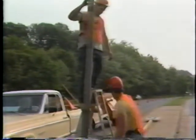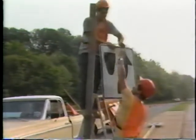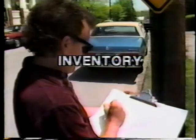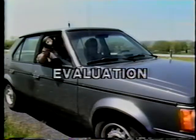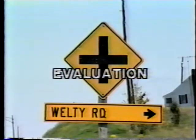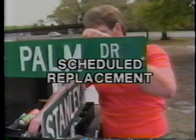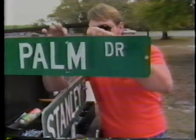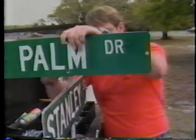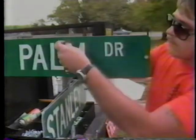While the details will vary, every successful program contains the same three basic elements: inventories of all signs within the system, evaluations and reviews for compliance with the standards, and following a schedule for routine sign replacement. The program can be as comprehensive as available resources will allow. The important thing is to have a program, one that's aimed at getting deficient signage off the streets.